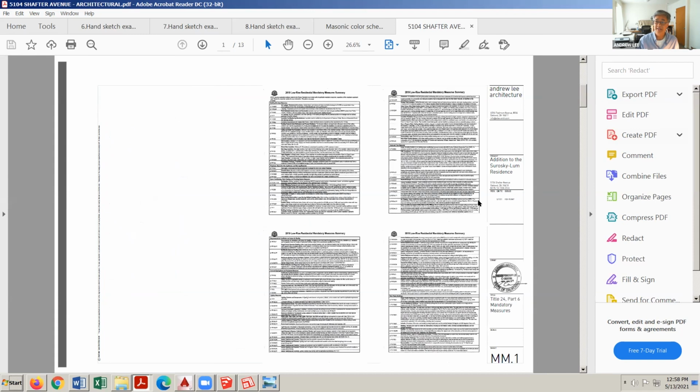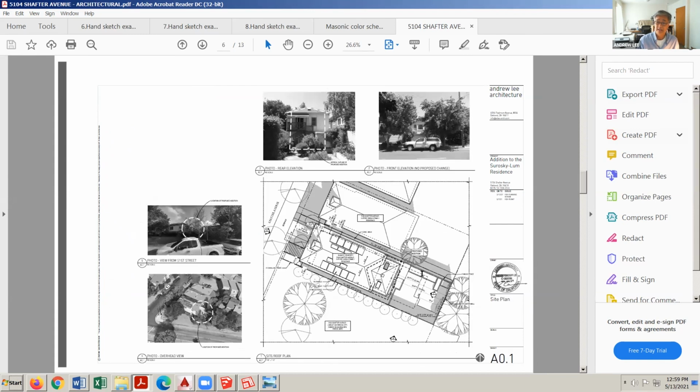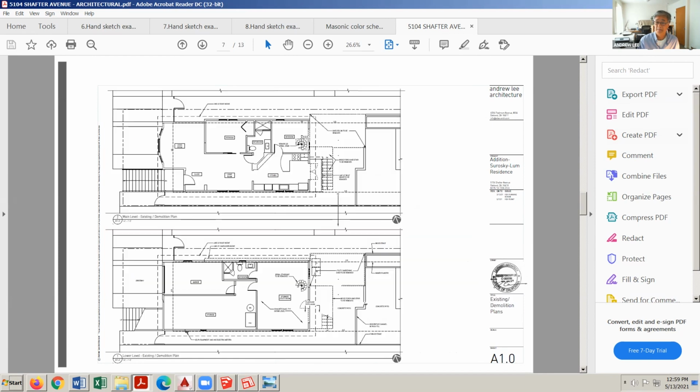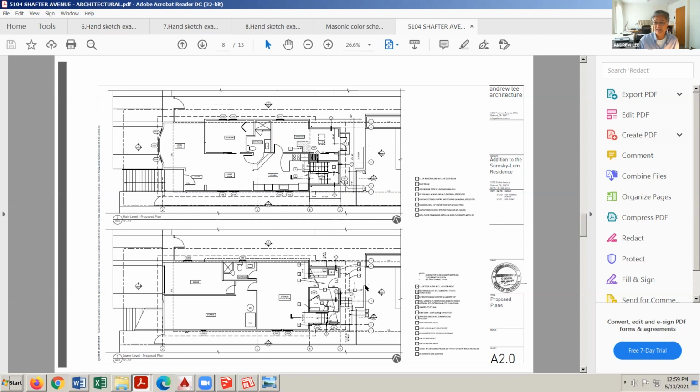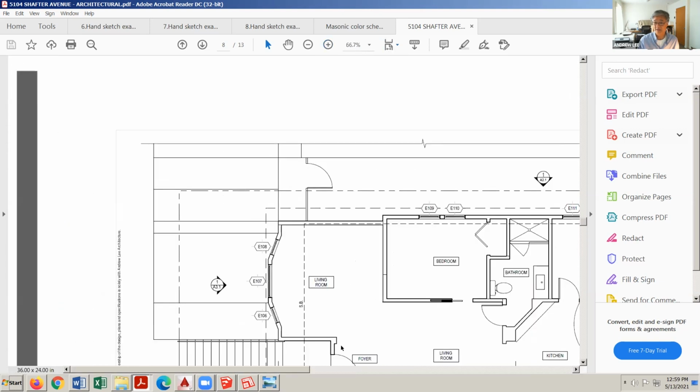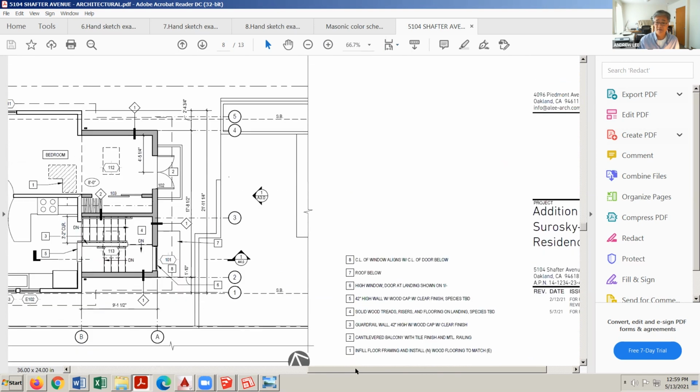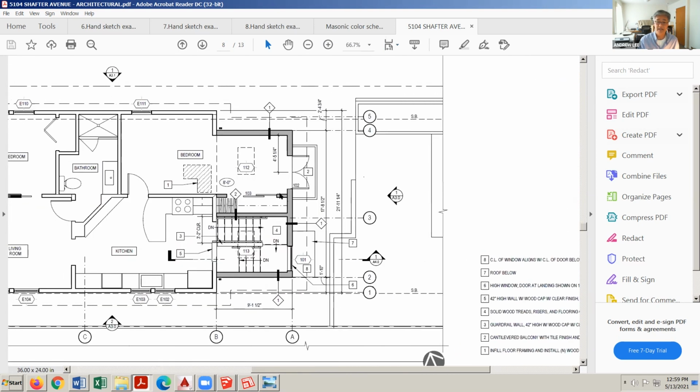So cover sheets, Title 24 documentation, site plan. This is located so north is up, the shadows are accurate. I've dropped in some existing photographs for the planning department. Demo plans, main floor and second floor. Demo conditions shown dashed, typical convention. New plans. I'll just zoom in on this really quick. So, anything that you need to see in AutoCAD or in a construction drawing, a submitted drawing, you can generate in Layout in SketchUp.